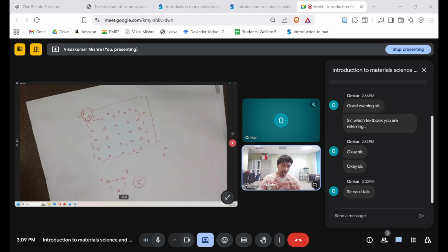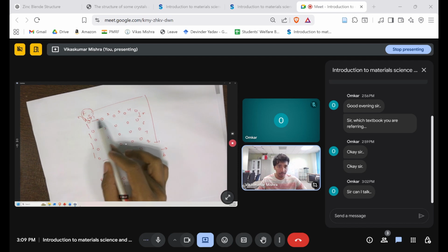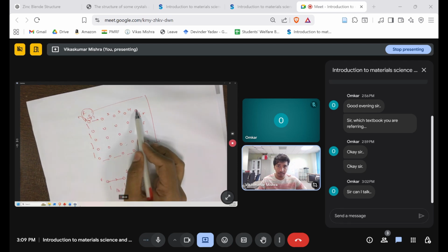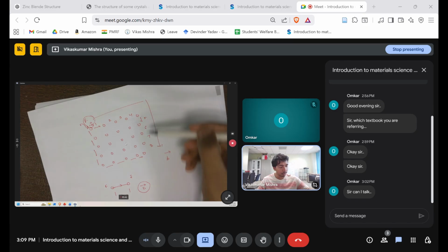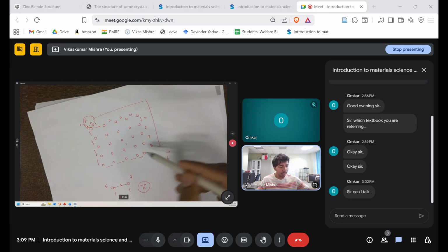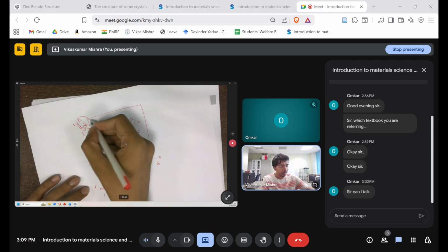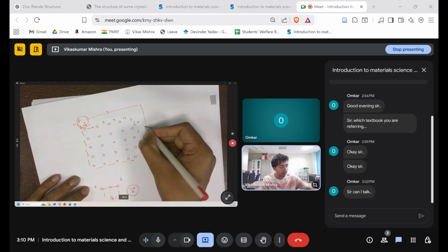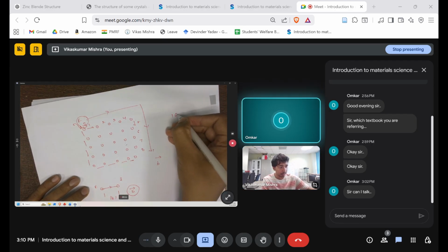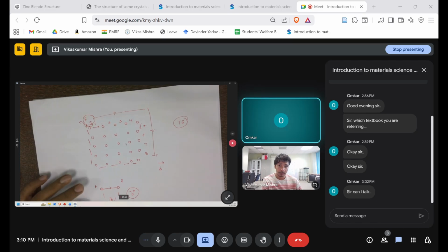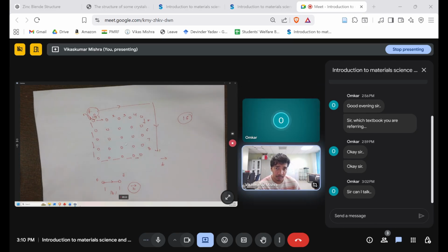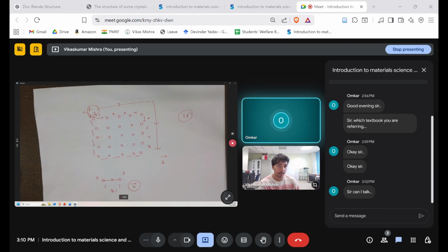If a crystal with a defect is given to you, you start counting from a particular step, go toward the right by a certain amount, go down, and then try to go back by the same amount. You have to make sure the counting remains the same. Let's say you went from left to right and top to bottom. The Burgers circuit is either completing the loop or not completing.